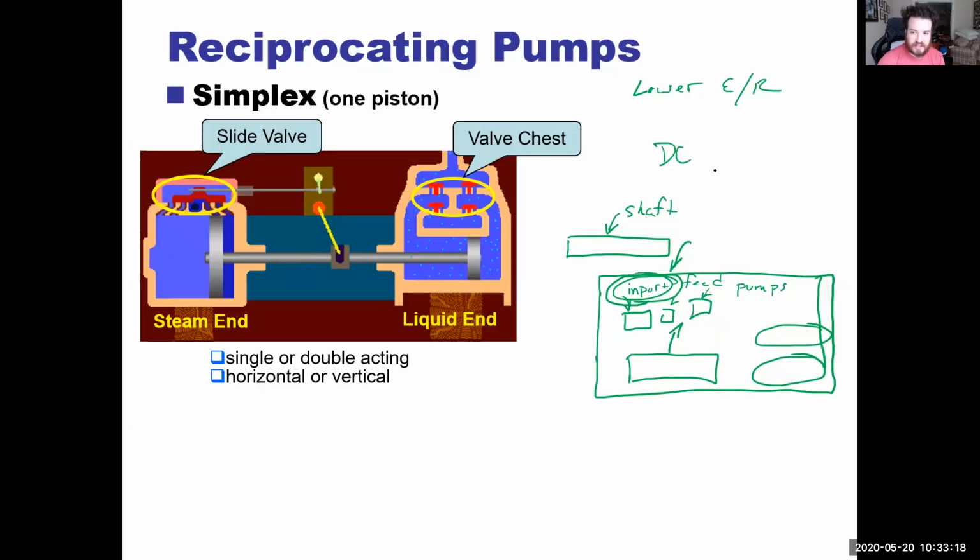We have our DC heater way up as high as it can be in the engine room, and that's a big vessel full of liquid. We don't want something that high, full of a movable liquid that can really affect our stability, unless we need to. The reason is that we want as much potential head as we can possibly get, and that's what gravity is giving us.